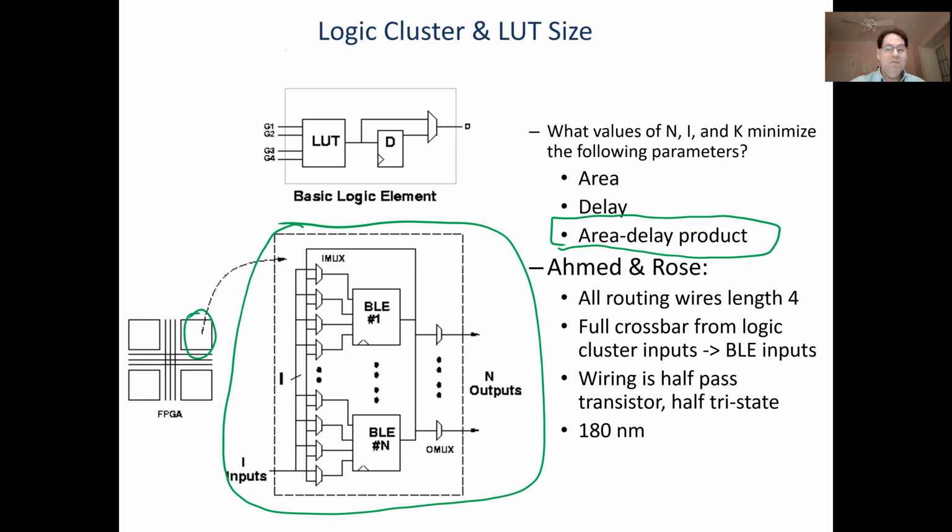So it is a convenient way to combine them. So that is one answer. But if you're trying to get the most processing out of a certain unit of silicon, you can basically get more work done by reducing area, which means you can replicate more LUTs or logic blocks, more functional units. Yeah, so as Camilo said, this gives us an estimate of the performance of the chip. Or we can reduce the delay. Okay, so reducing the area would allow us to have more parallelism in the same area budget. Reducing the delay just allows us to clock it faster. The area delay product, therefore, is basically 1 over throughput per unit of silicon. So it is an estimate of the performance of the chip.